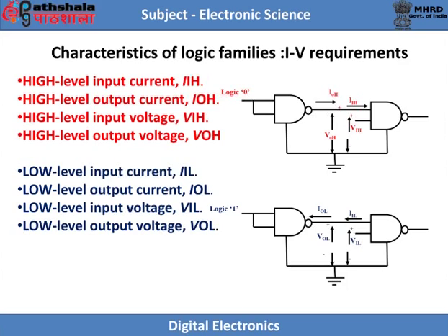This is the maximum current flowing into the output pin of a logic function when the input conditions are such that the output is in the logic low state. It tells about the current sinking capability of the output. The magnitude of IOL determines the number of inputs the logic function can drive when its output is in the logic low state.